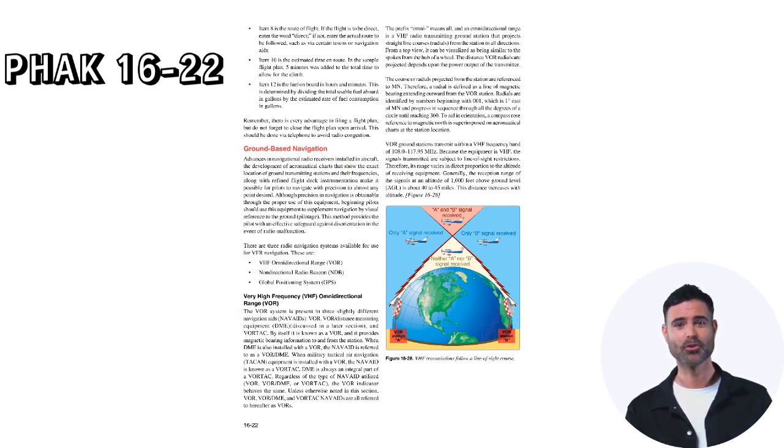When DME is also installed with a VOR, the NAVAID is referred to as a VOR DME. When military tactical air navigation, TACAN, equipment is installed with a VOR, the NAVAID is known as a VOR TAC. DME is always an integral part of a VOR TAC. Regardless of the type of NAVAID utilized, VOR, VOR DME, or VOR TAC, the VOR indicator behaves the same. Unless otherwise noted in this section, VOR, VOR DME, and VOR TAC NAVAIDs are all referred to hereafter as VORs.